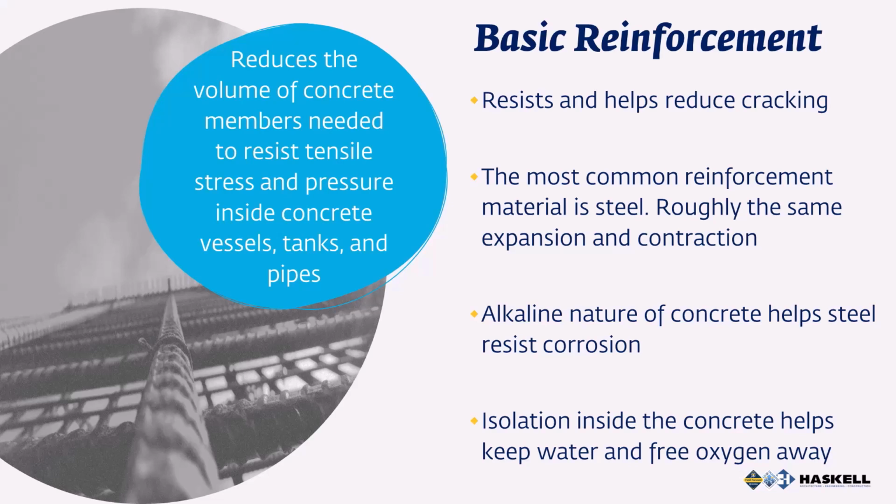The most common reinforcement material is steel. Steel and concrete tend to expand and contract together with temperature changes. The alkaline nature of concrete may help keep steel reinforcement components from rusting. Its isolation inside the concrete helps keep water and free oxygen away.